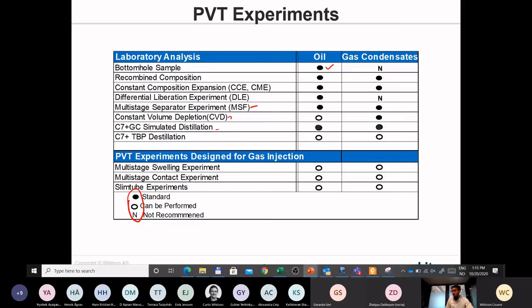Exactly, yes. So the first requirement is that you need an equation of state model. I believe you may have it. And then the second requirement, you need an in situ representative composition with an equation of state model, and you just simulate the CVD experiment with this PVTI software. You should know at what average reservoir pressure in the future you want to estimate the composition.